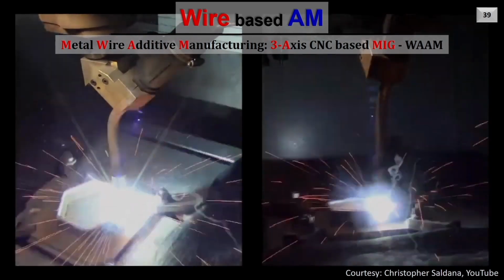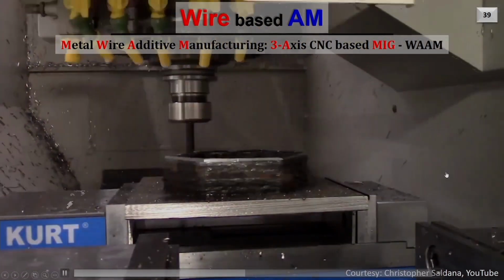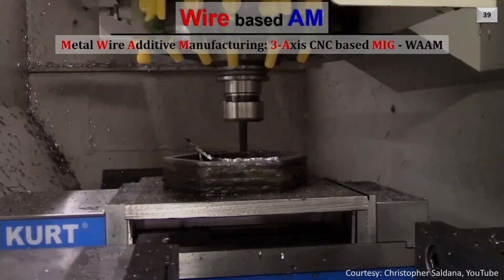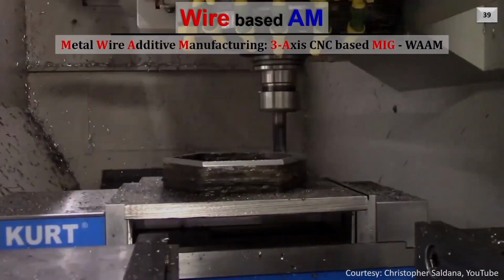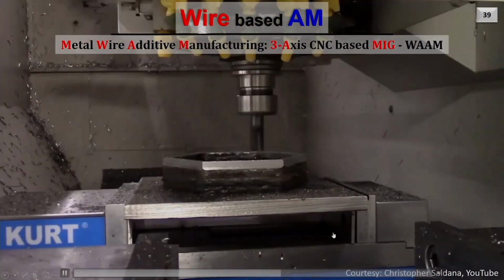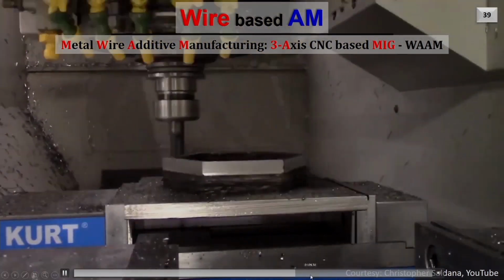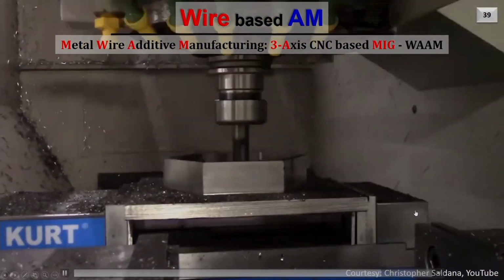As it is a retrofitment on a CNC machine itself, simultaneous machining can also be performed. Such processes are called hybrid wire arc additive manufacturing processes. So here we first deposit the near net shape on the part, and then we finish mill it on the same machine to obtain the final finished object.